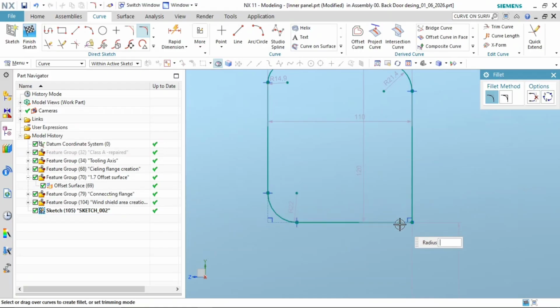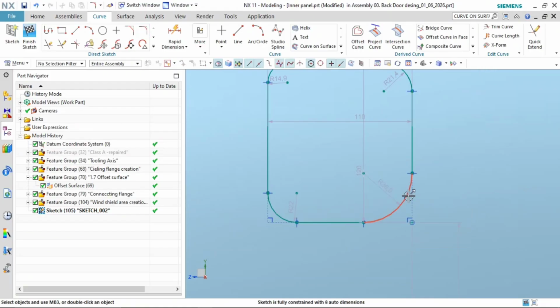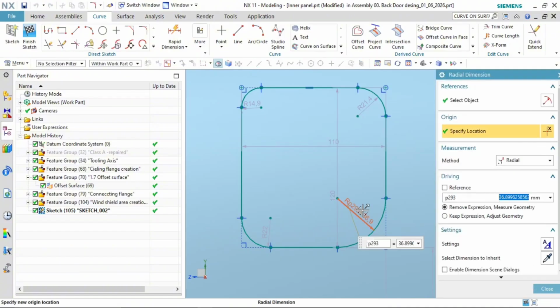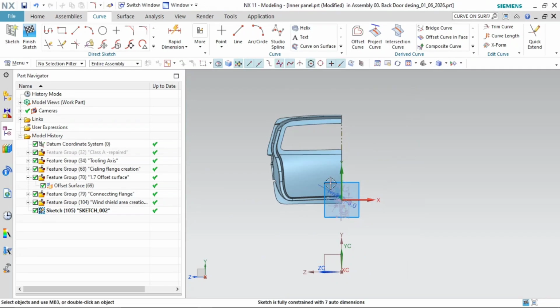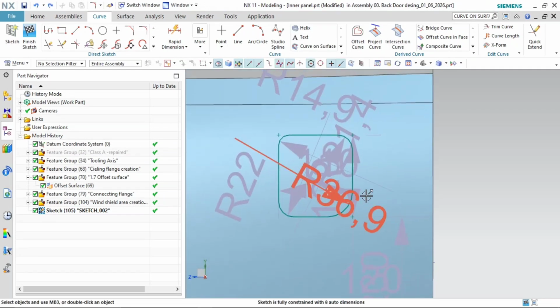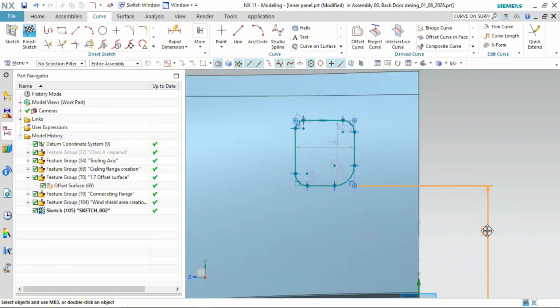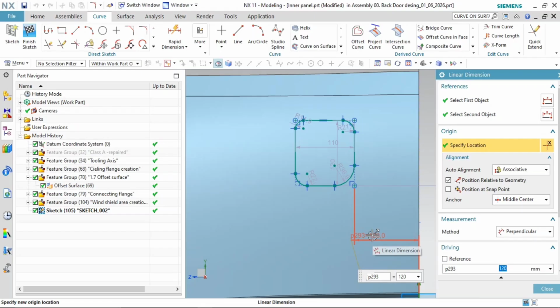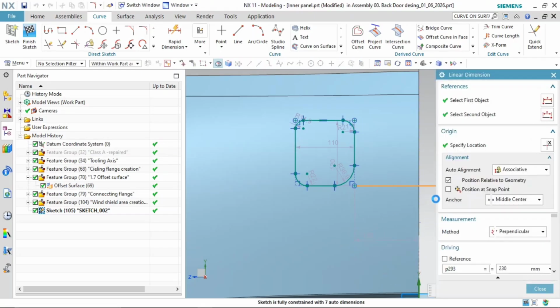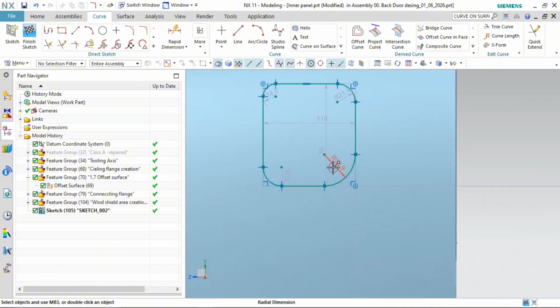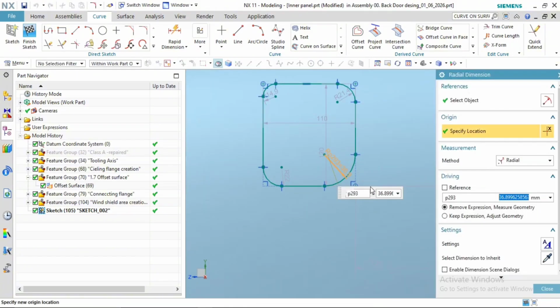And then afterwards you can double click on it and give the fillet radius however you want. So in my case I'm giving 3 values. Control Z. But before that you have to constrain it properly. Double click on it, enter. The automatic dimensions which are formed will help us. The value I am taking is 10, enter.